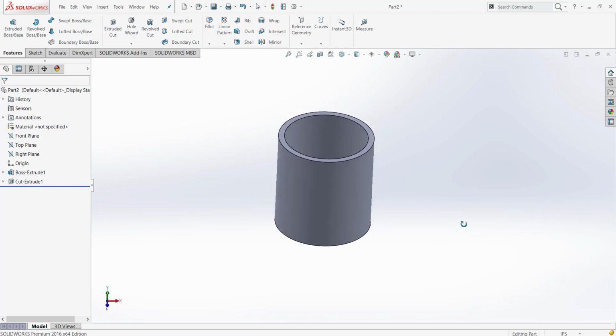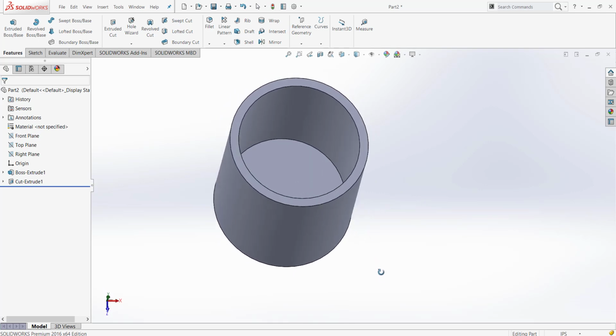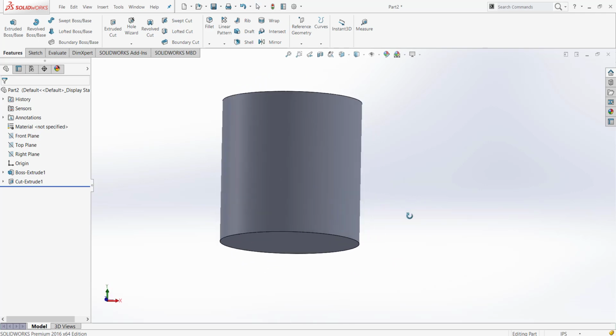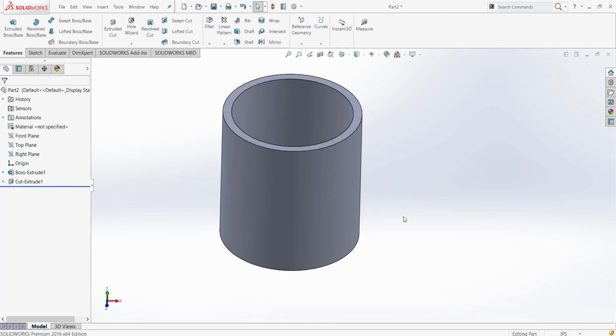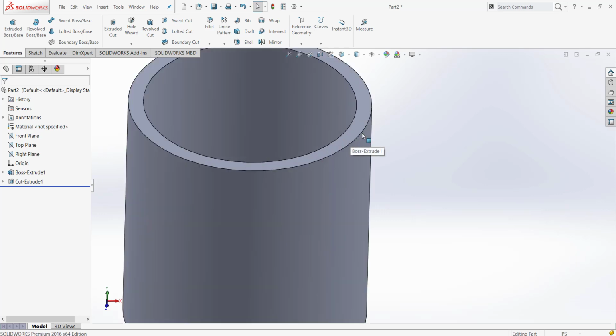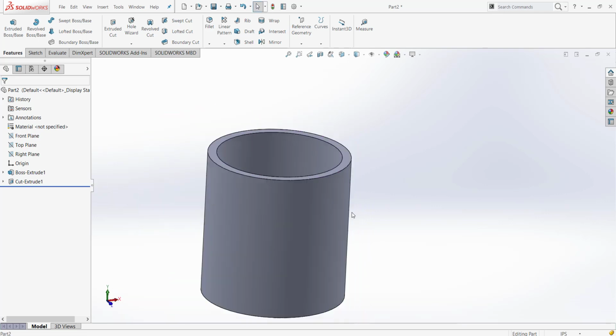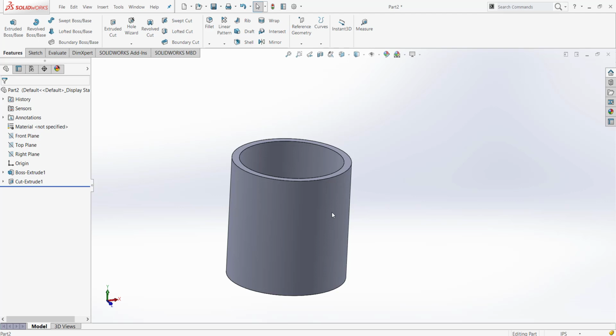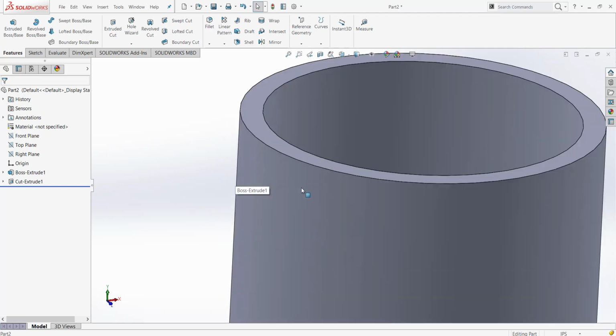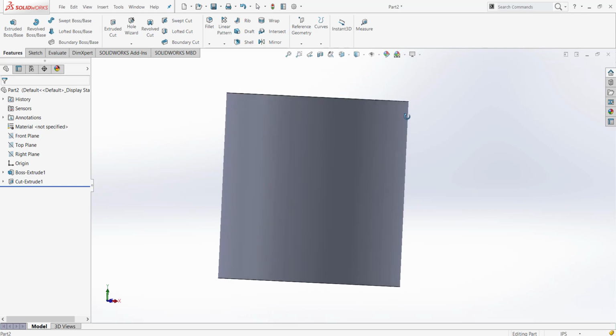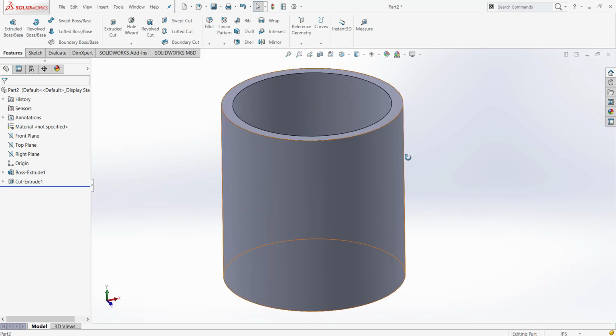I will add a couple more features to make it look a little bit more like a realistic mug, and just features that help consumer products in general. For instance, in reality, you wouldn't want to be putting your lips around a really sharp edge like this, even if it was out of clay or porcelain or plastic, anything sharp. This is theoretically a perfectly sharp corner, and you wouldn't want to have this. In reality, that's not even possible, but if you manufacture this, it would come as sharp as you have indicated it to be, as sharp as they possibly can.